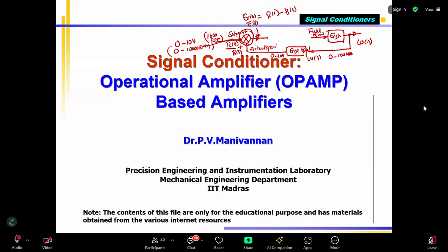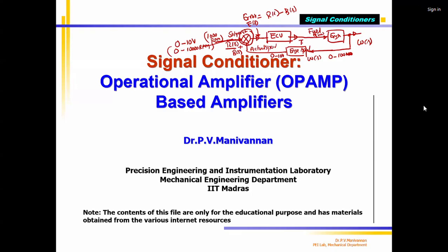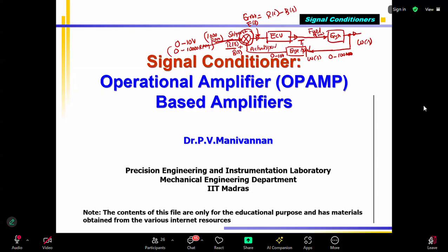Now the error signal is given to a controller. This is your ECU, electronic control unit. The electronic control unit generates the fuel pulse width, pulse width modulation, T PWM. We know that the PWM pulse width will be varied depending upon whatever torque you want to generate. The width I call TW. This is the injection pulse width.